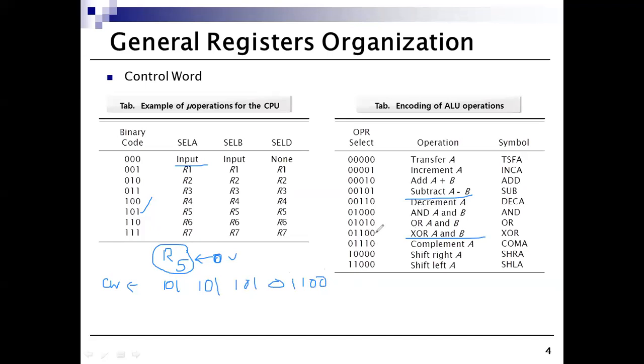XOR is better than subtract, because subtraction requires circuitry, whereas a logical operation doesn't require much hardware, as it is bit to bit logic.